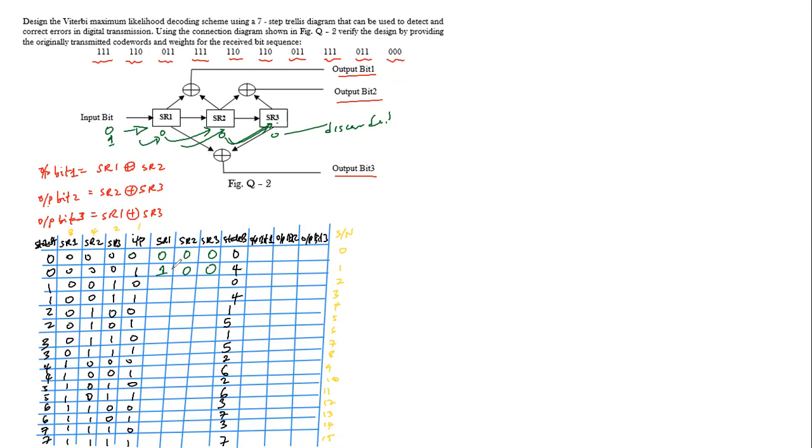Is that correct? So now the shift register holds a 0. What was held originally was 0, so that moves, this moves, so every other thing moves. So it's all zeros now. So 1 was held originally here by S3, so it's discarded.